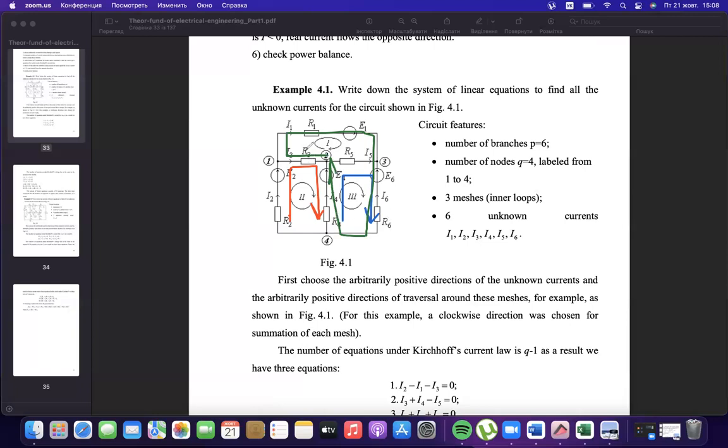First, second, 4 resistors. It just increases the number of elements, the number of constants inside the equation. That is why if we don't have a current source, generally we take only internal meshes, but if we want, we could also take external ones.